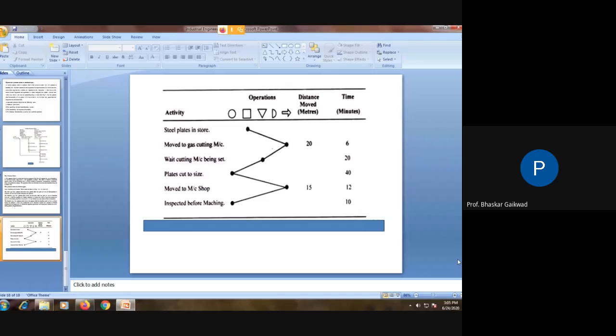To bring the raw material from the stores, we have to check it, so inspection is there. Bringing is transportation. Bringing it near the machines is transportation. Delay for die setting. Once the delay is over, then we'll start the machines, then operation will start. Once the operation is over, either the OD or ID may get pierced or blanked on the raw material, and then the finished product you will get at the bottom of the machine. So this is the sequence of the manufacturing.